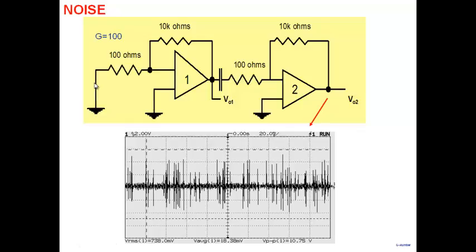So the noise property of an amplifier is also very important. Most of the time, if you're not pushing the limits, the input referred noise voltage is so low that you don't bother about it. Your signals are much larger, and you don't encounter noise. But if your signals are very weak, you will encounter noise as a fundamental limitation in your amplifier. That is something you will have to wrestle with as you go towards lower input voltage and lower input power. Noise becomes extremely important.